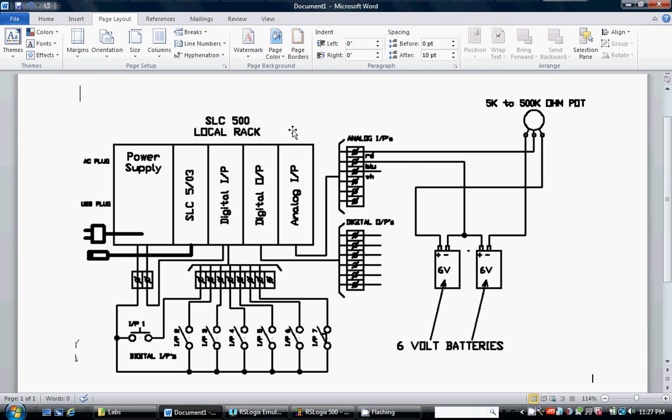The card should be set up for 10 volts plus and minus, and as we know, it's a 16-bit integer word, so the value of counts obtained from the card will range from 32,767 to minus 32,768. So plus 10 volts will give me 32,767, minus 10 volts will give me minus 32,768. So that's it for the diagram.